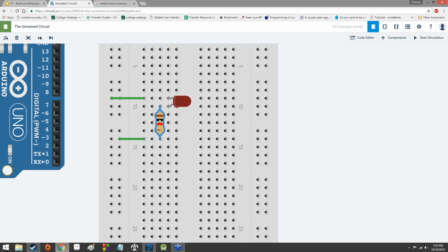Since 1000 ohms is too many ohms, it's too strong. We need a lower powered resistor. Well, we can just click on it over here, the upper right-hand side, we've got a properties menu where a name is listed and a resistance is listed. And we can actually change the resistance value. So I'm going to change this to 330. I'm not going to say kilo ohms, I just want regular ohms. Select ohms from the drop-down menu.